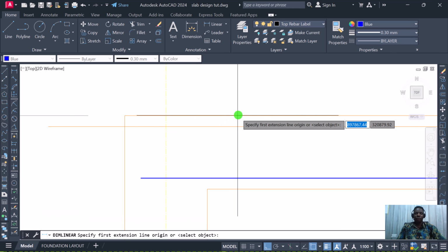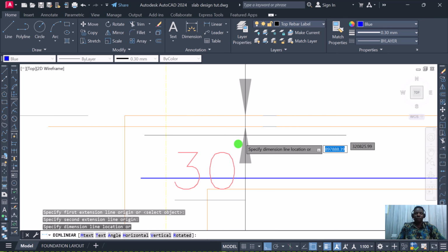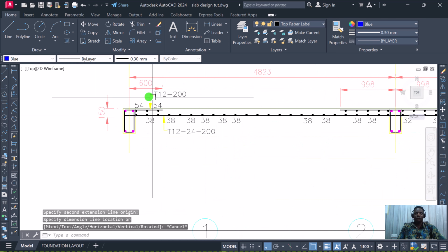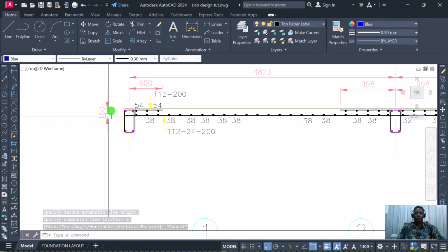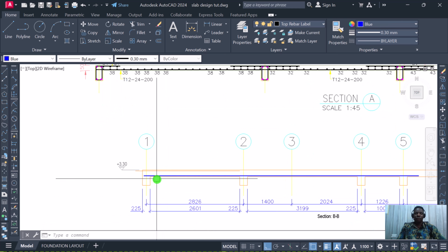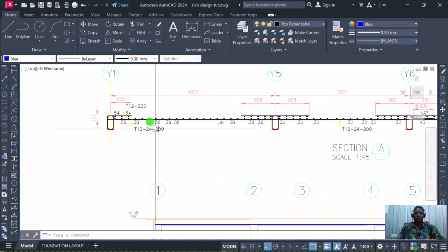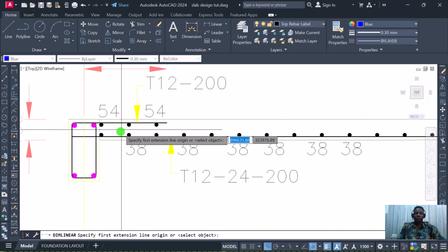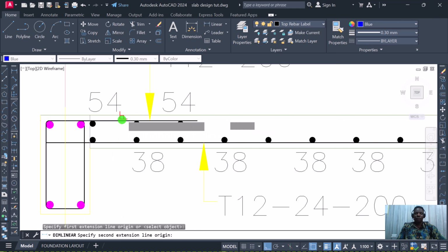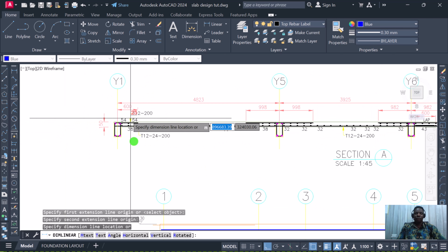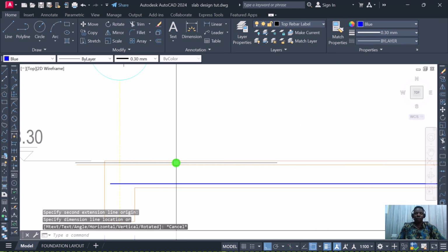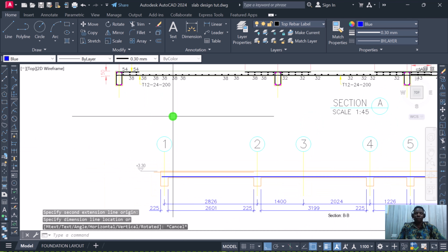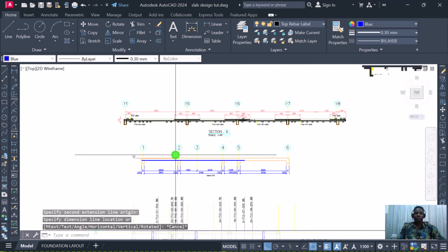Because in the example we have, like I said, this is just a guide. This is just a guide for you. But if you look at here, we're having a thickness of 150, whereas what I'm doing is a thickness of 200. So you just need to know. And we have a concrete cover of maybe 25, but here we'll be maintaining the concrete cover of 30. So this is just like a guide that you use to do your basic slab design.